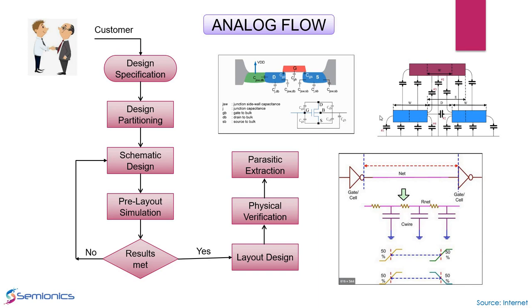Assume that you have done some routing. This is metal 1 and metal 2, and this is the substrate over here. So when parasitic extraction is done, the tool will extract the parasitics of this metal 1 with respect to the substrate, metal 1 to metal 1, that is the sidewall cap, between metal 2 and metal 1, and even with respect to the substrate. So all of the capacitances, coupling capacitances, sidewall capacitances, fringe capacitances, all of this is taken into account, right?